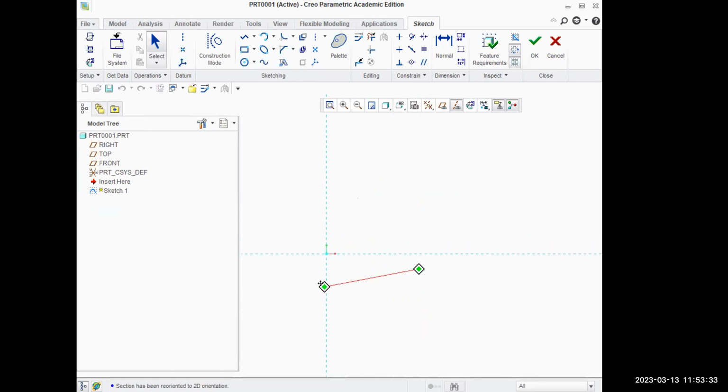Now this time we'll try to make use of this simple mirror command here. Okay. So this mirror command is useful when we have objects which are maintaining some symmetry about a specific axis. Now I assume that whatever the second figure is there, that is having symmetry about, let's say, the y-axis.